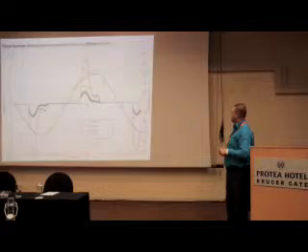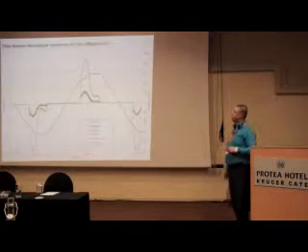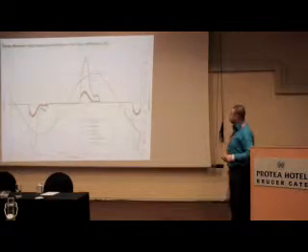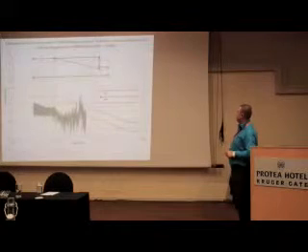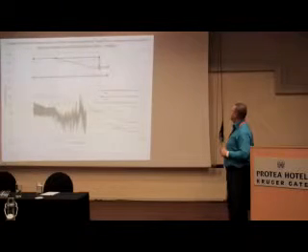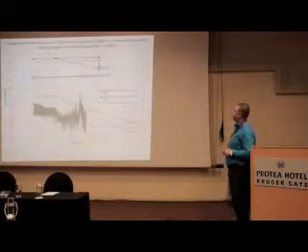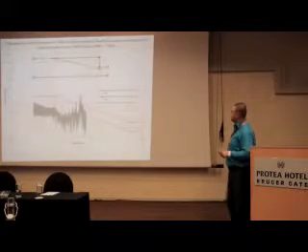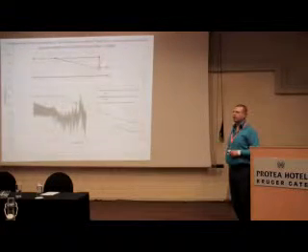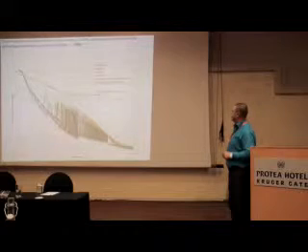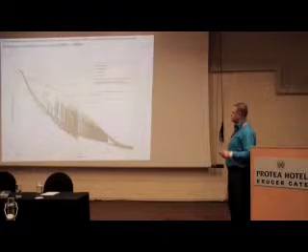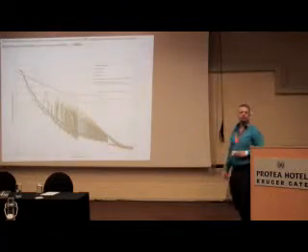This is the voltage. We can see that when we turn them all on together, the channel is mostly affected. This is in current. And here is a comparison of the harmonics of all lamps combined with the maximum allowable PLC signal strength in the CENELEC band. So this is only from 3 kHz to 150 kHz. As we see, we are still safe, we are under the maximum allowed signal. In this case, this is for the broadband, and these are the EMC levels, and we are also still okay with this.